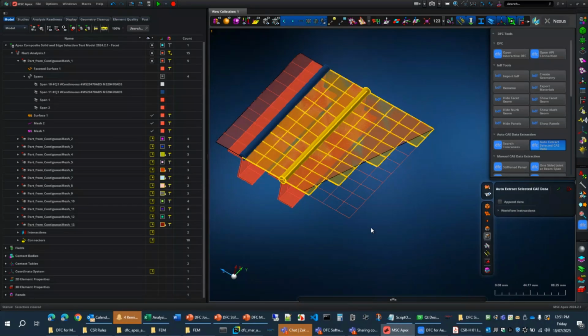If you've got it modeled as discrete joints, the loads stay linear. So if you've got it modeled as discrete, you have to then redistribute the numbers by yourself outside. Correct. Because at the end of the stringer, you'll get peaking loads that won't be correct. Correct. Okay. All right. Thanks.